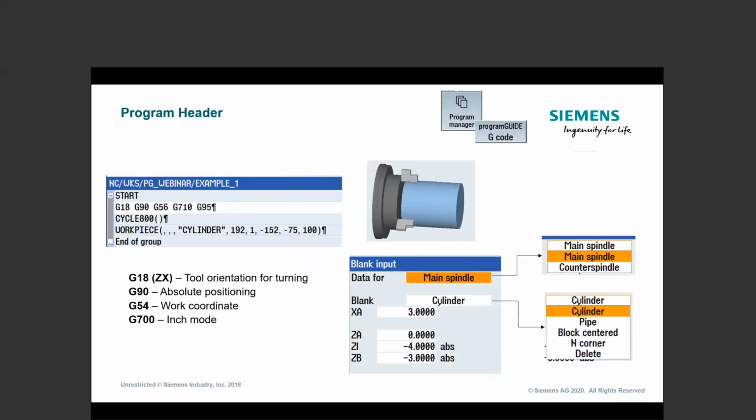From there, when it comes to working with your workpiece blank, if you haven't been on a multi-spindle lathe before, you do get the option of picking either the main spindle or the counter spindle. So we can work in either direction or on either side first. We could transfer from the main to the sub or the sub to the main. You don't even ever have to transfer. If you happen to be lucky enough with one of these machines and you're doing a simple job on the main spindle and you want to use the sub spindle for a different job, you could absolutely do that. You would just set up the blank to work off the counter spindle, and then it would work like a standard single spindle lathe.